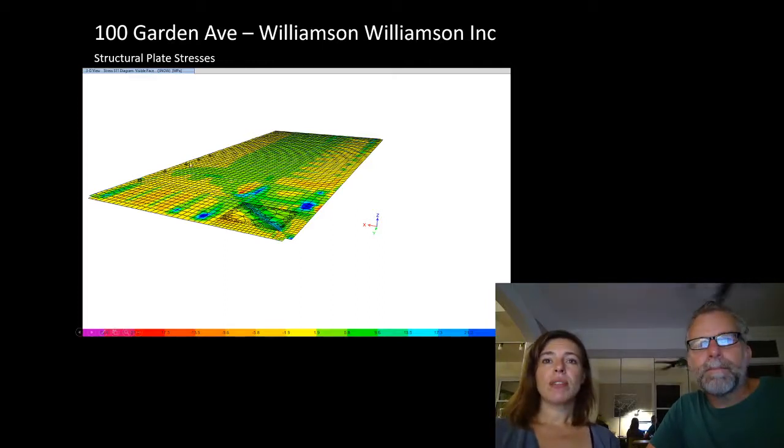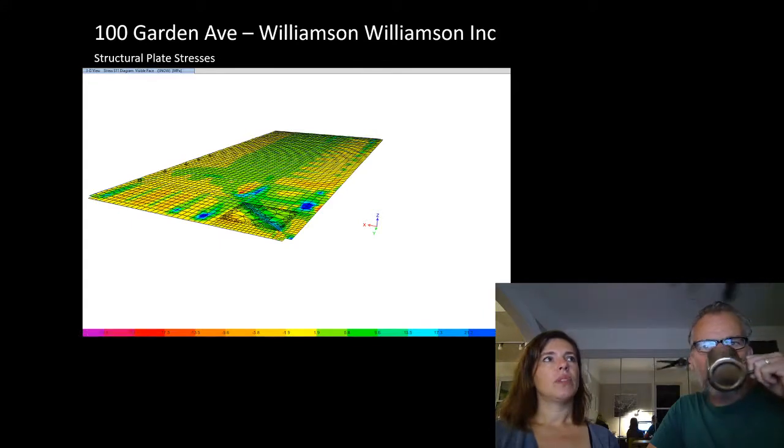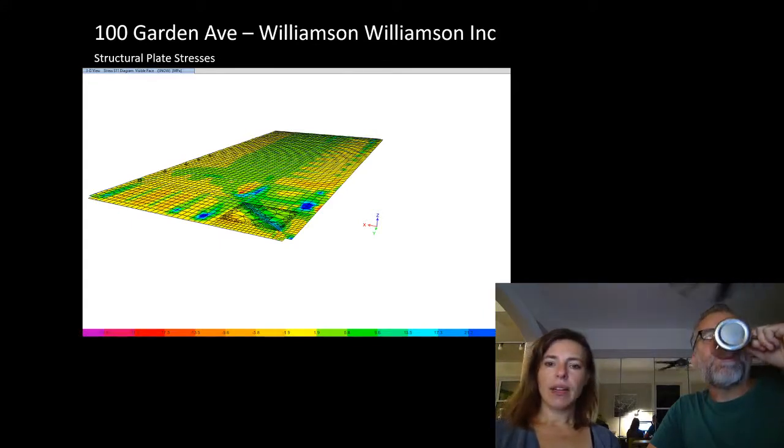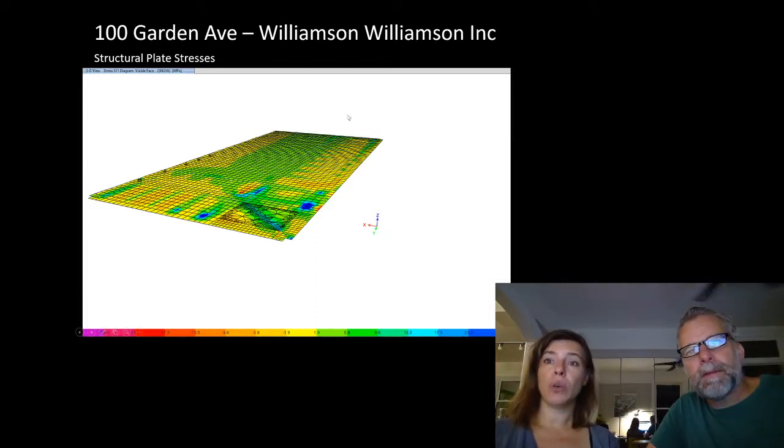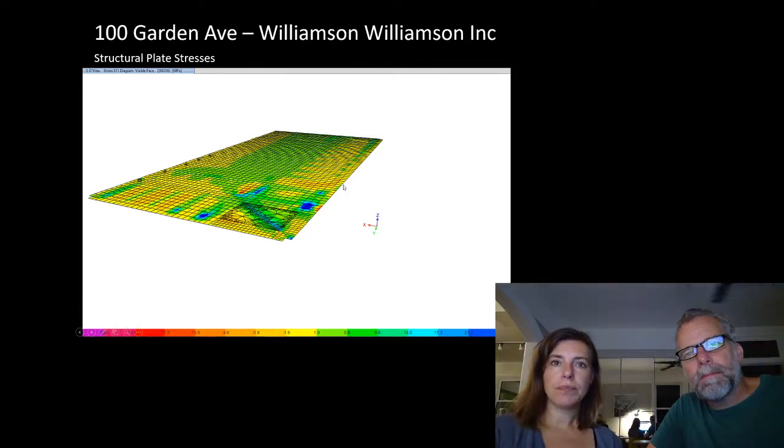In fact, the stresses for this were so low that to show you anything graphically, I changed my scale to be 25 MPa. So, 1, 2, 3, 4, about a tenth of the actual capacity of steel, just to show you what the stress profile looks like on it. So this is under snow. Our steel sees our worst stresses right here and at these locations here.